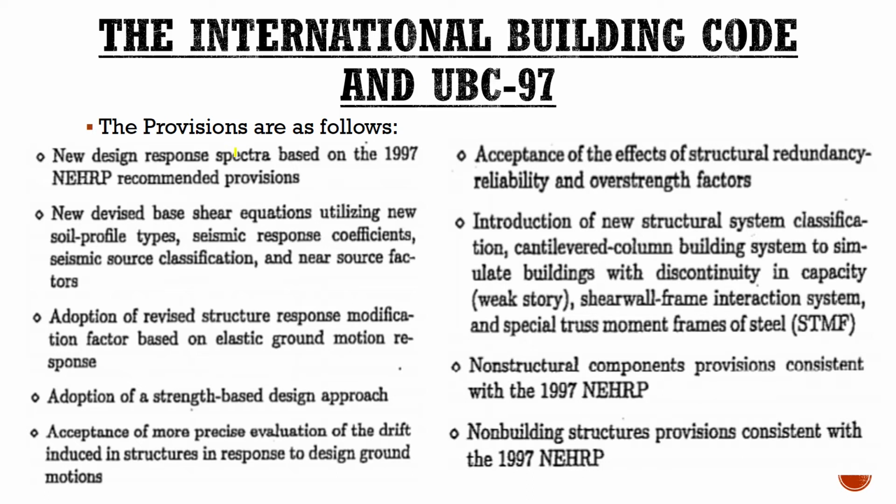New design response spectra based on 1997 NEHRP recommended provisions. We will discuss this response spectra later. New force-based shear equations utilizing new soil profile types, seismic response coefficient, seismic source classification, and near source factors.